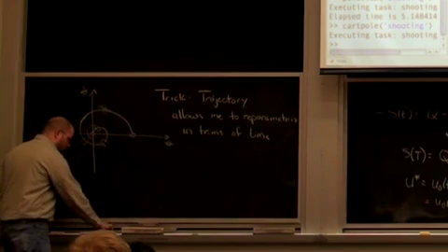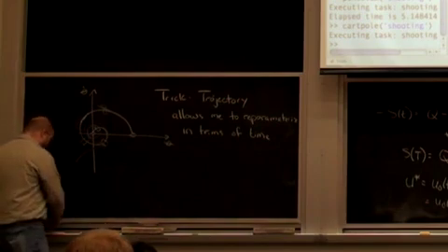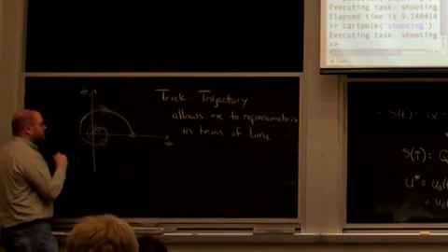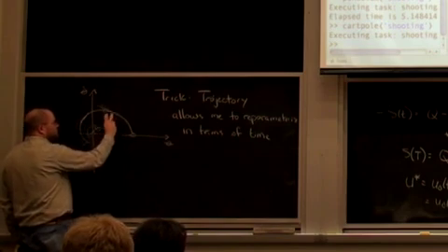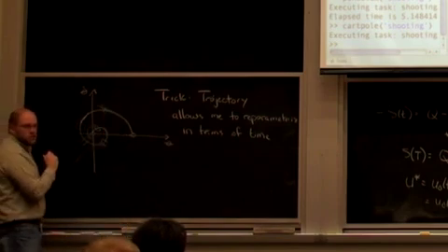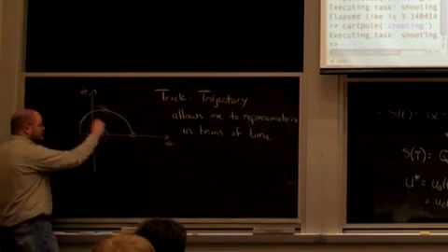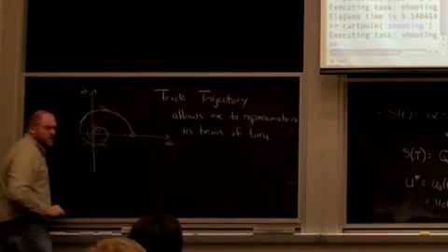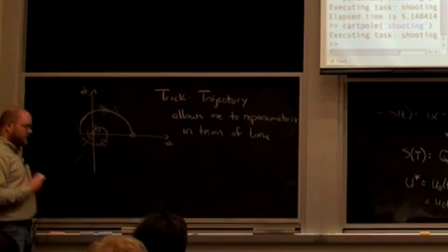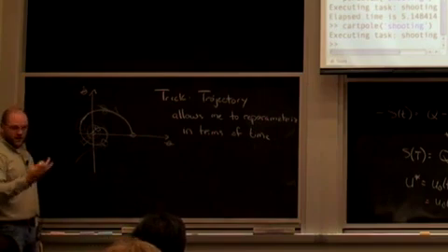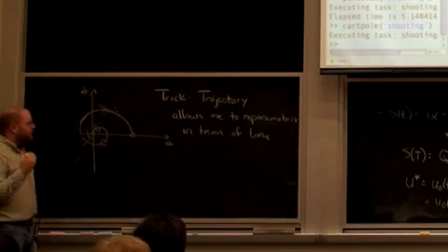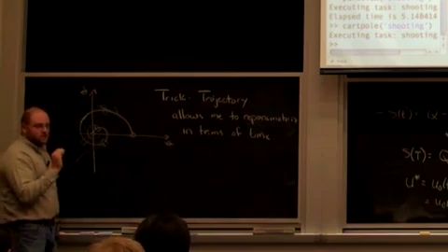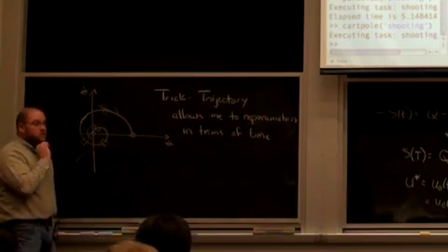So Philip asked a nice question. He says, why do I just blindly start marching forward from time 0? Maybe if I have a controller, I should just look for the closest point in my trajectory, and then instead of indexing off time, index off some sort of phase, some fraction of my trajectory, and then execute that controller. You can do that. I wish you the best if you do that. But my suspicion is that if on every dt you pick the closest point in the trajectory, you're going to chatter like you wouldn't believe.